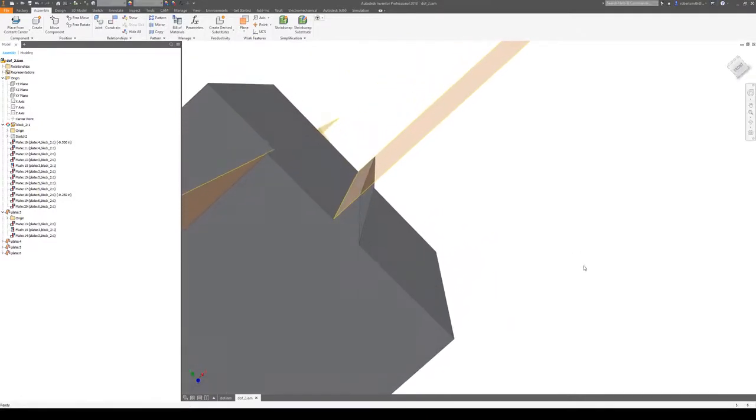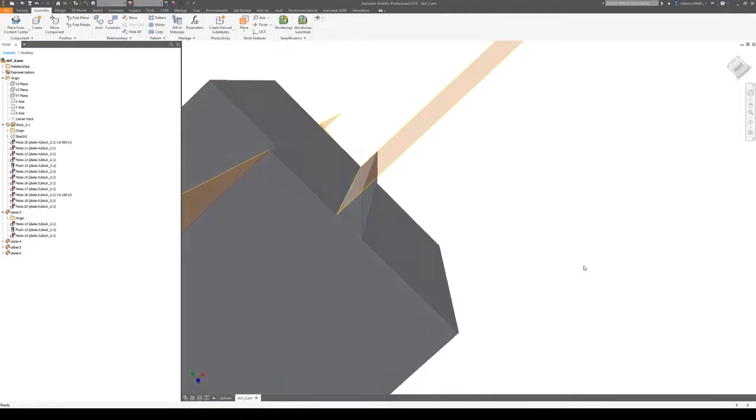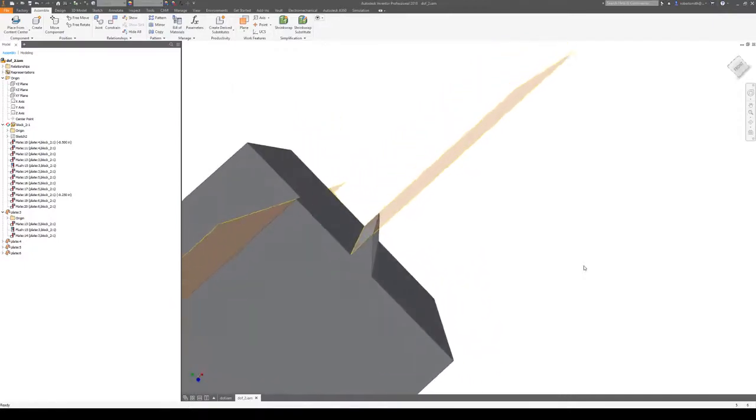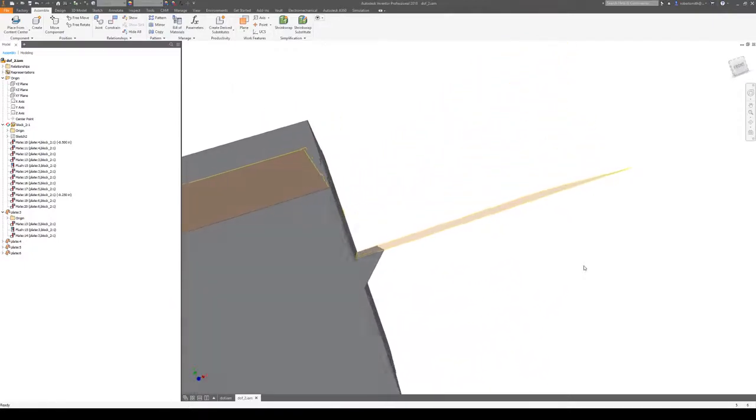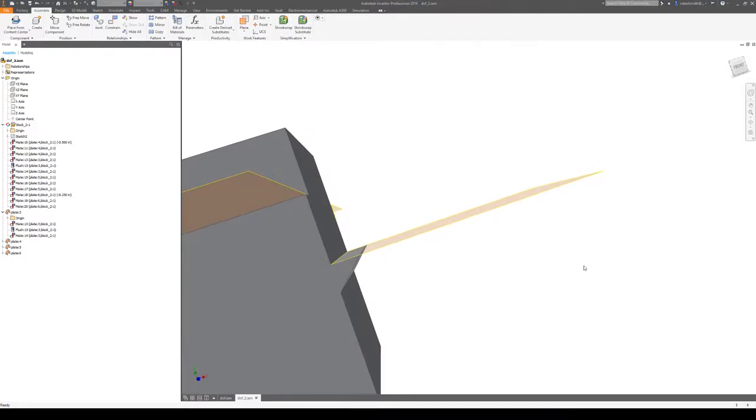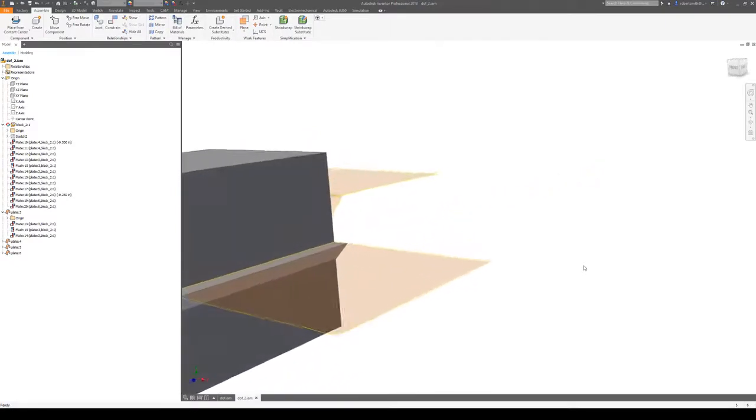The weld beads tend to be a lot more complex than what we've shown here, but that doesn't preclude you from including them in the model if it's really only there to help join dissimilar element types like we have here, or even spread out forces and spread out stresses to avoid concentrating stresses at a single location. You can put your weld bead in there, and it's basically effectively putting in a step, right, where we can overlap the shell elements with the tetrahedral elements.